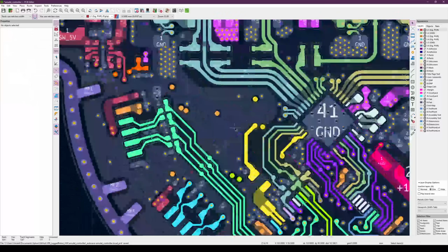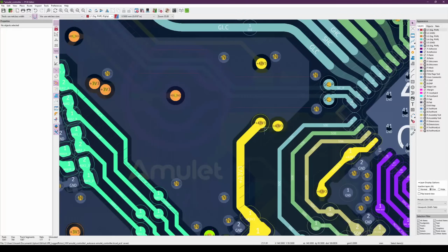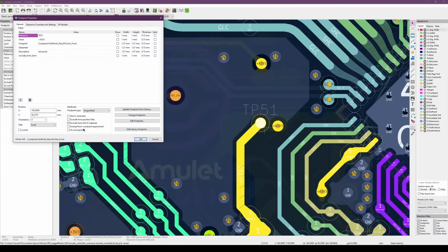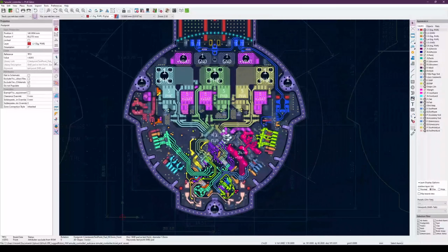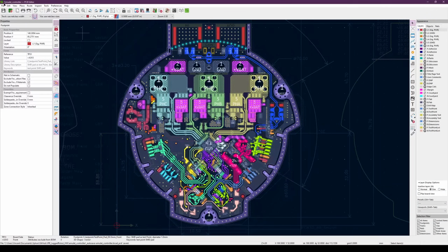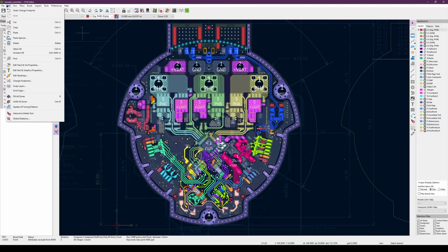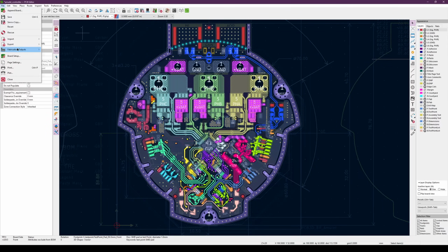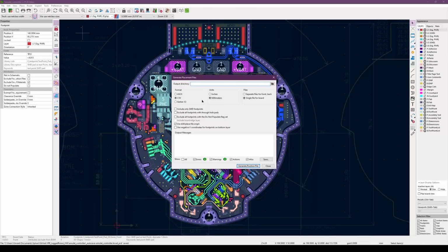And you will see here that if I select this footprint and go in the fabrication properties, now it is no more excluded from the position files. This means that we can plot the centroid file and get the coordinates of these test points. So now we'll just go in the fabrication outputs, then go in the centroid file, which is the POS file.